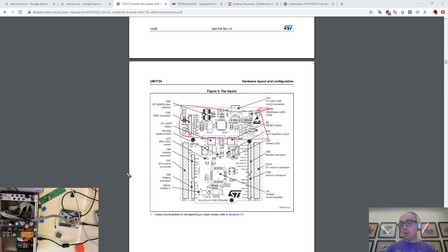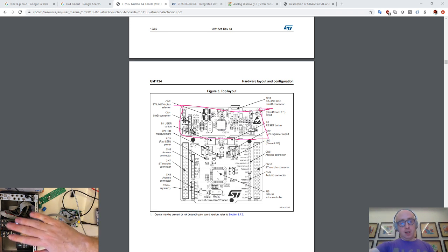So if you look in my overhead camera in the corner here, I have one of these, and I've built a little adapter that connects. Now, this SWD header here has 6 pins on it. Ground, power, which confusingly goes from your board to the Nucleo, not the other way around. So it doesn't power your board, which is super annoying. You have to power your board yourself, which I'm doing from this Erica Synth Pico case. So I've got power going into my module. This is the module here.